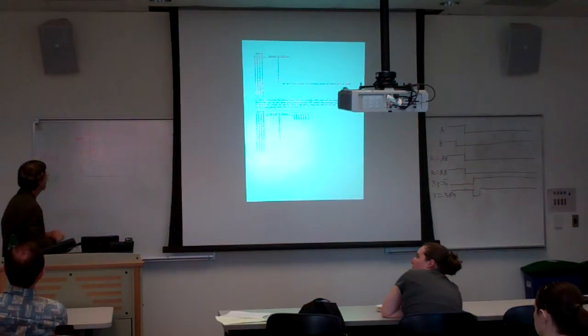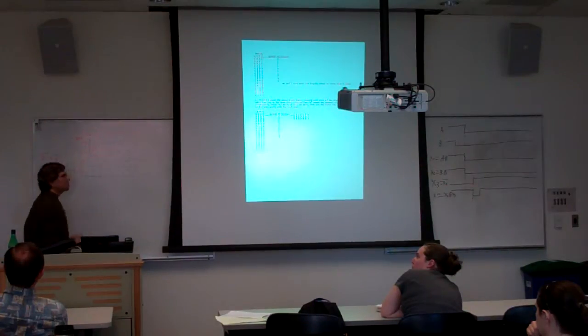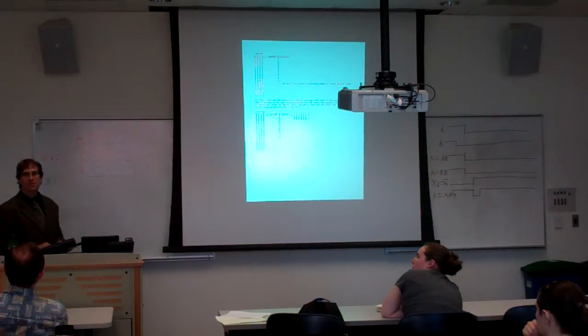Or you could just use one or the other. If you cover it like this, then you've absorbed this term also, which is good. You're trying to get as many ones covered as you can, because you want to use as few rectangles as possible. But you can drop it down by one.